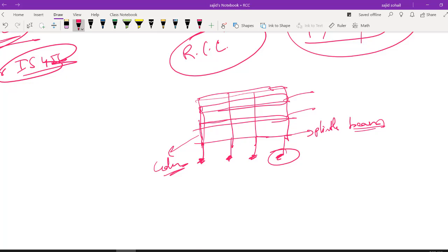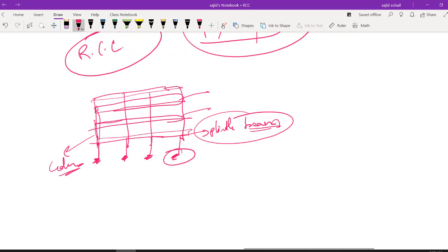Everything is clear for you. और यहाँ पे plinth beam भी आएगा, don't forget that. Many people directly go for first floor, second floor. अरे यार, plinth पे भी एक beam रखना पड़ता है, we call it a plinth beam. And sometimes in some structures you can see the difference between floor to floor is very high, right? So अगर आप rich buildings पे चले जाए, the buildings which are expensive, you will be seeing the floor to floor distance is very high. If it is like 3 meters, 4 meters or 5 meters कुछ इस तरह का है, then obviously I will go for an intermediate beam also.